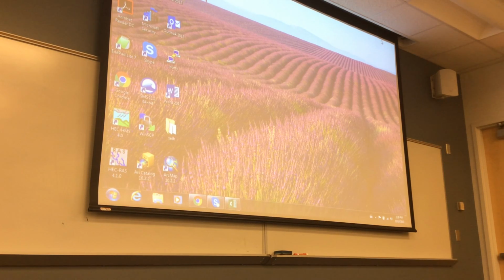So the hydrograph starting on this reach is the sum of these 2 hydrographs that will be routed through reach 1. But watershed C is also producing a hydrograph that's coming in here. And then what's coming into reach 2 is this hydrograph plus those 2 hydrographs that were routed to reach 1. And then on reach 2, we will have this hydrograph plus those that will get to your bridge, plus the contribution of this little watershed towards here. Did it make sense what I just said? This is the key here. Okay, great. So we're going to use a model to represent this.